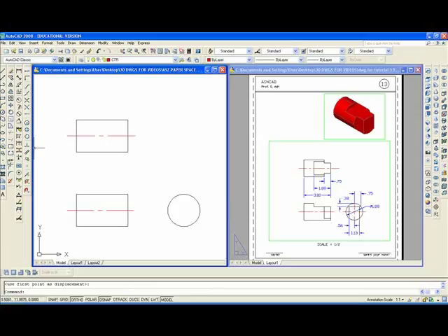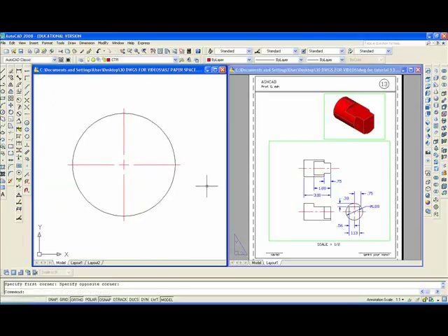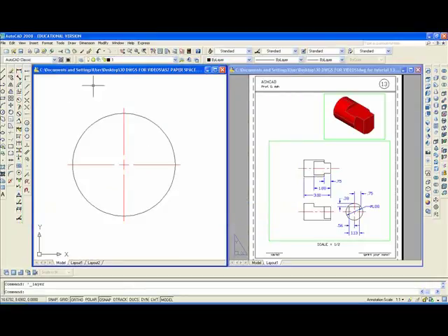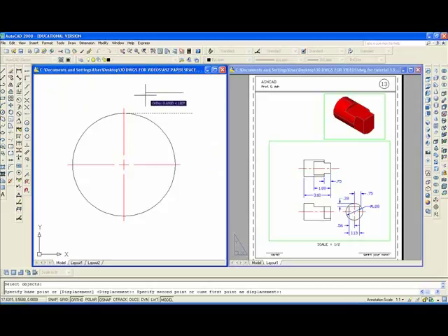And we're going to go to dimension mark, which is here, and put that. I think I'll start with the right side view. First off, we're going to draw, go back to making layer 1 current. Okay. I'm going to draw a line from this intersection here and move it. M enter, move it back like that.